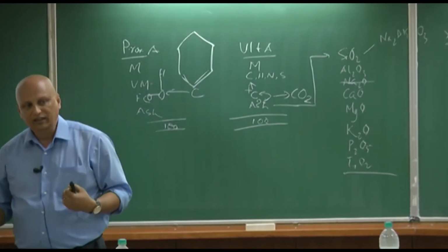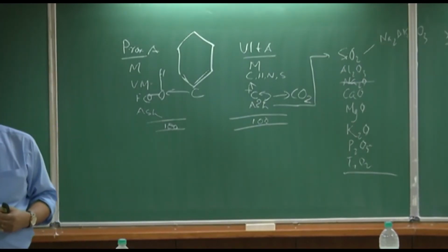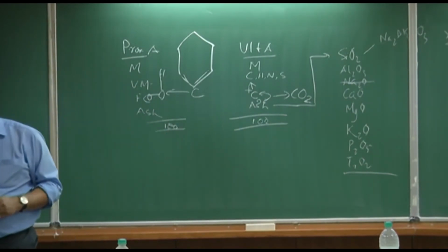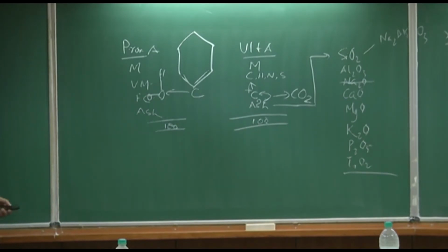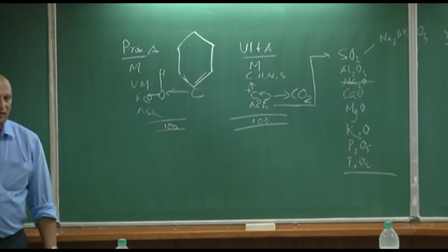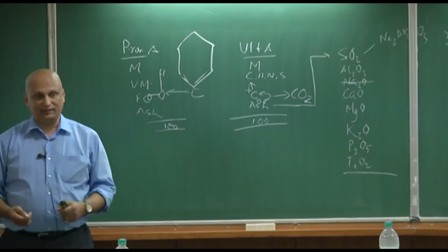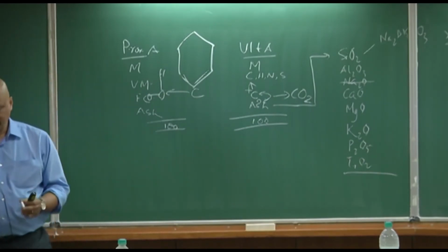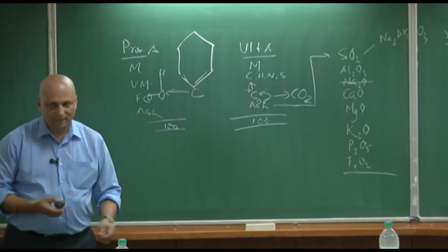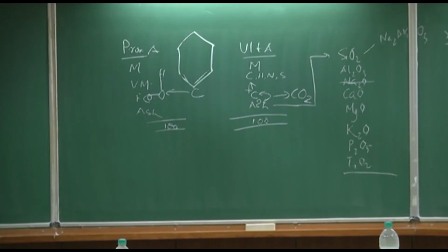So when we do the stoichiometric calculation to find out, for a given ultimate analysis, how much air is needed, we subtract this amount of oxygen, because the understanding is that this oxygen will take out some of the carbon as the bonds break. The oxygen will come out as carbon dioxide.